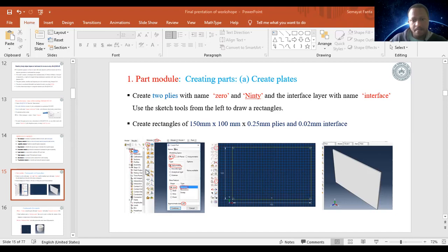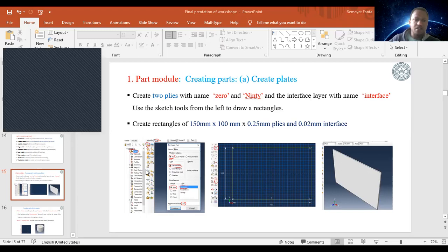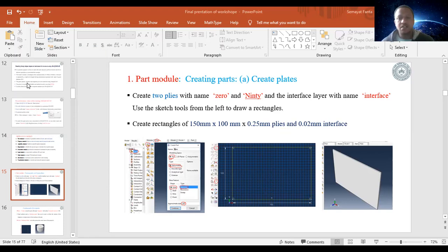And then from this point to 0, 0. Yeah, done. Now let's extrude it with the thickness. Done. Extrude to 0.5. Let me use 0.5 millimeter for the time being, E-3. So this is the plate.